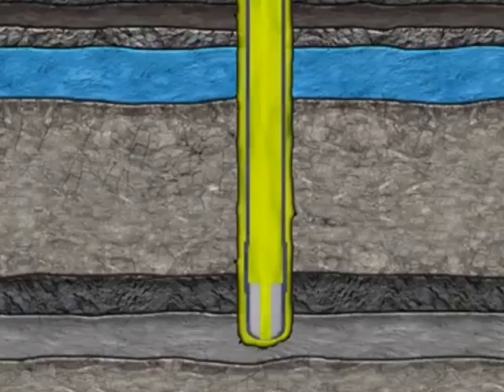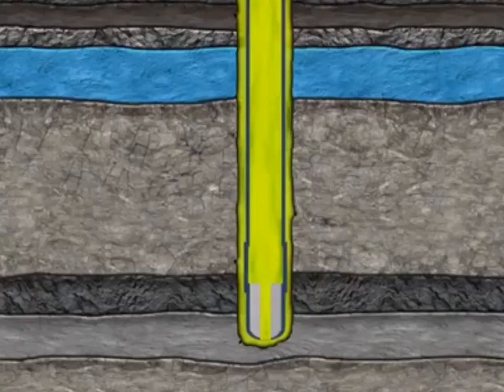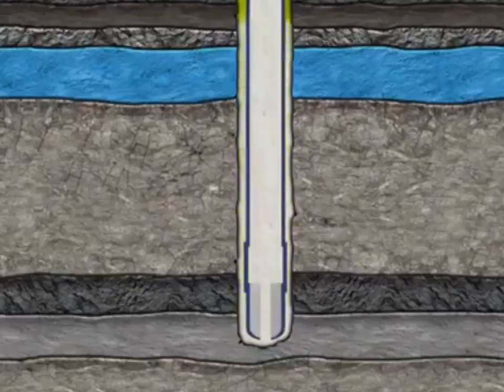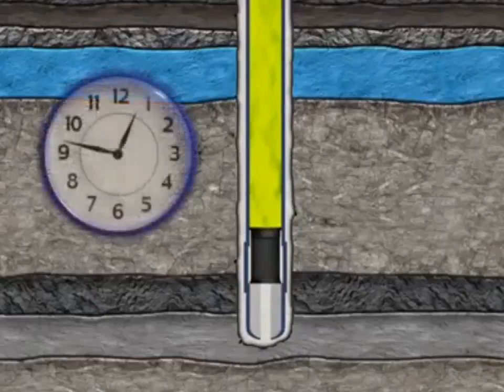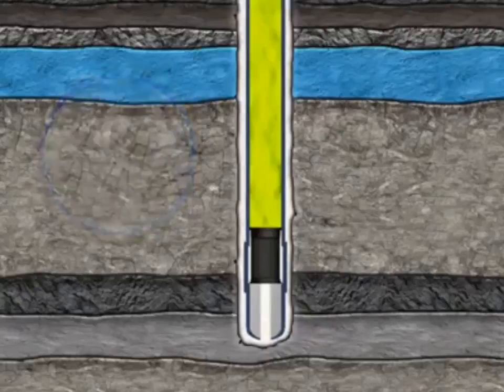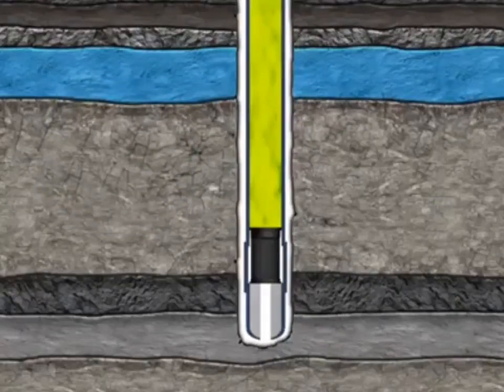In order to secure the laid casing string to the formation, cement is pumped through the casing shoe at the bottom of the well, letting the cement flow between the casing and the formation. To allow further operations in the well, the cement requires sufficient curing time. Once the cement has dried, the seal of the aquifers is established.